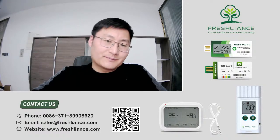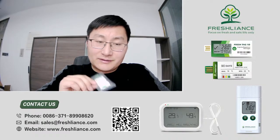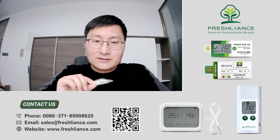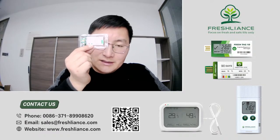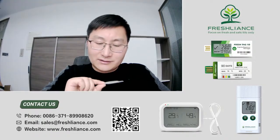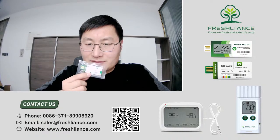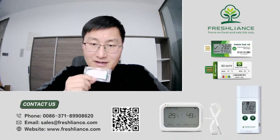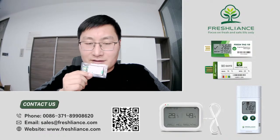Most important thing I want to introduce to you is the LED status, LED indicators. You see there are three LED lights: red, yellow, and green. The green indicator flashes 3 times. It means data logger starts working. The green indicator flashes every 30 seconds. It means data logger is in working status.